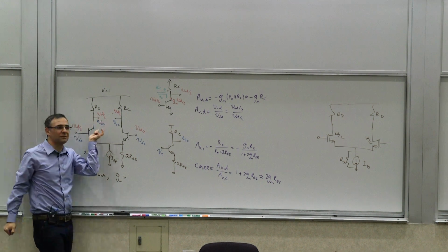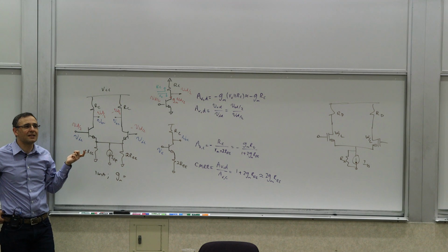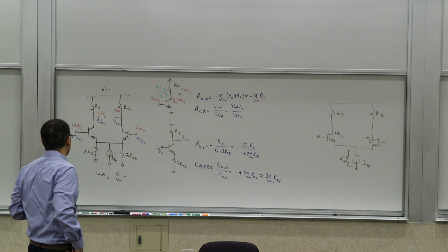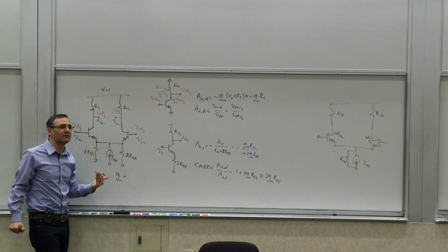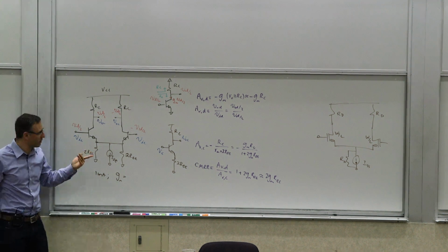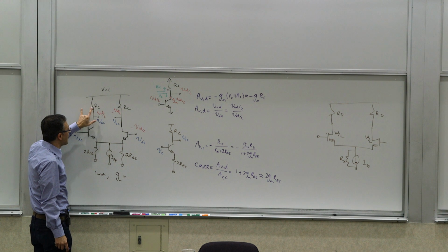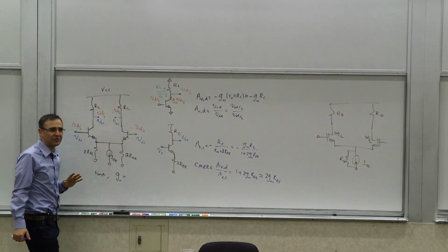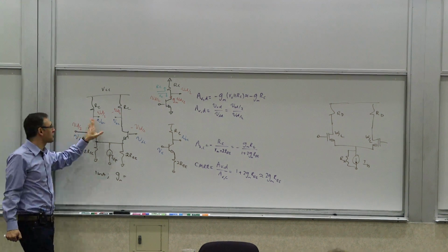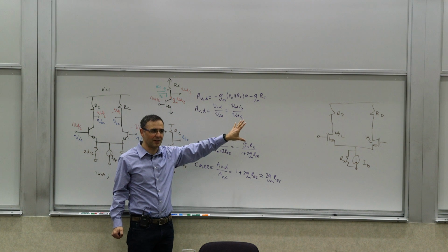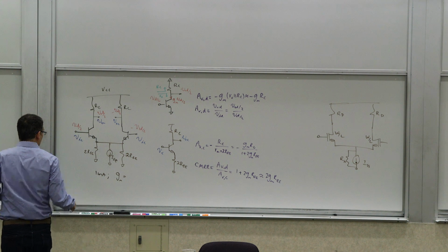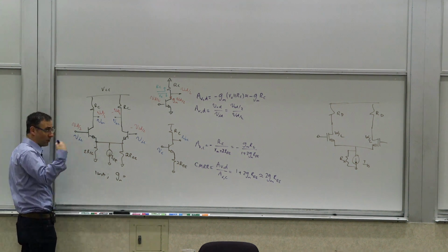If you're taking the output differentially anyway, you would not see any of the common mode, right? If there's no mismatch, yes, exactly. That's exactly right. There is another element, which is the conversion of the common mode to differential, which we haven't talked about yet, but we can talk about now. In the absence of mismatch, if the two sides were perfectly matched, you will not see any effect on the differential. As long as you're amplifying your signal completely differentially and carrying it through, it's not a problem. So there are two situations where this becomes different, and both of them are important.